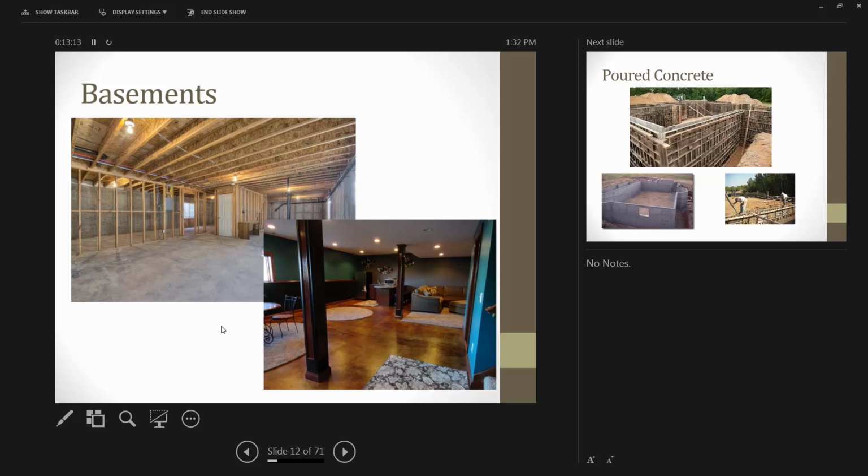And so when you think about if a basement's going to go down 7 feet, 8 feet in the ground, you've got the entire basement slab and a lot of the basement walls in contact with 54 degree temperature. If you're trying to keep your house at 70 degrees, and you've got 54 degrees outside, you've got a 16 degree delta T constantly all winter long. And which way does the heat want to go? Hotter to colder. So it's constantly conducting from inside to outside. So basements are another big problem area.